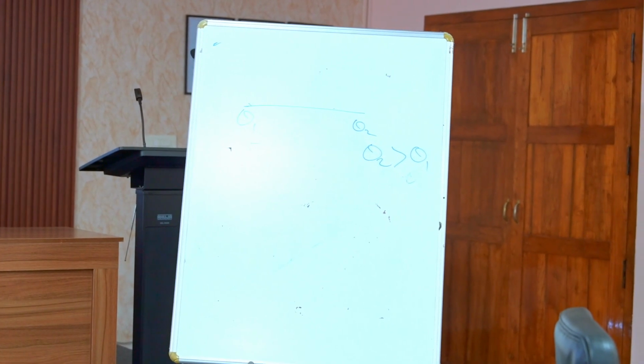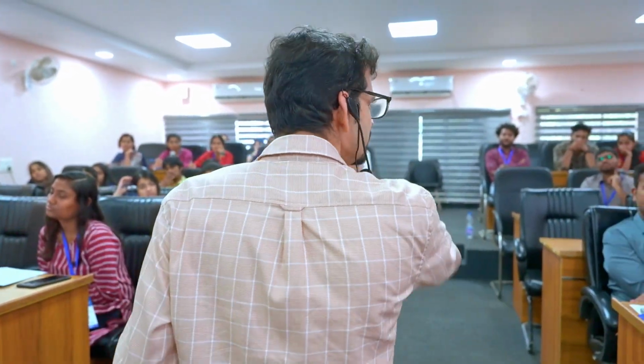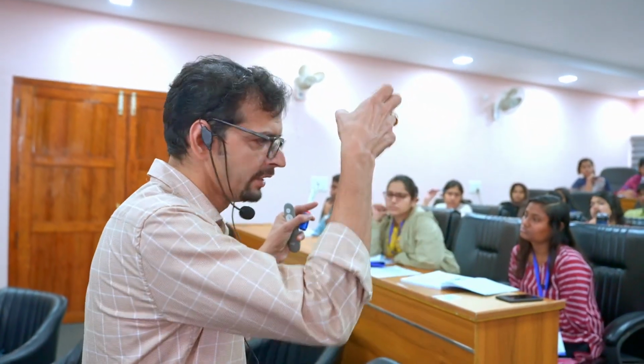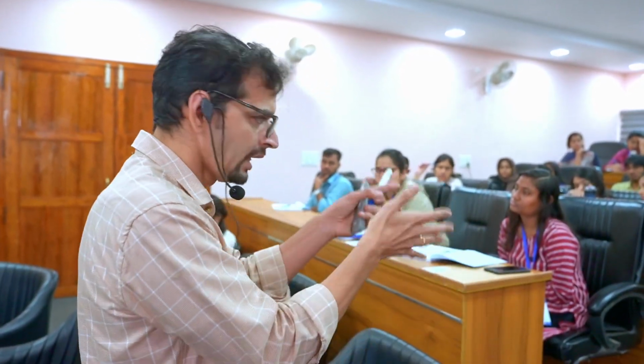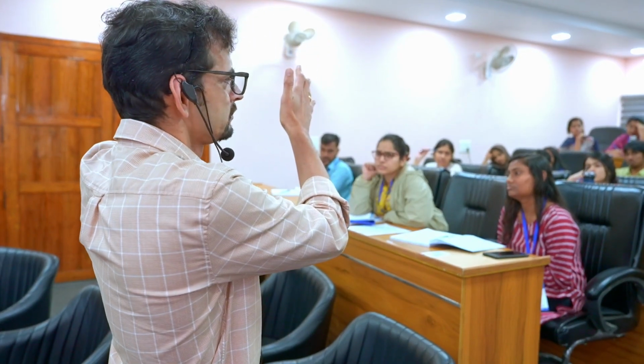The answer you gave is that if it moves, it will move only to theta 1. The other question is whether it will always move. The question is clear, right? I have a wettability gradient surface with a significant contrast in wettability. I put a droplet, and definitely theta 1 will be different from theta 2. Theta 1 will be more wettable, so it will spread more. Perfectly okay. The question is whether the droplet will move automatically.